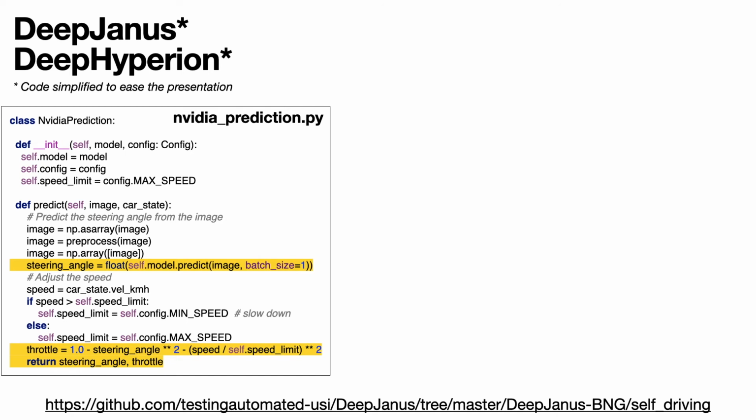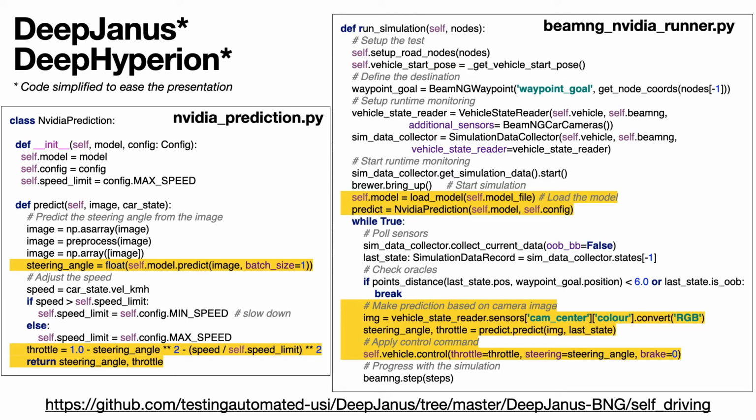Once you have this model, once you have this component available, assuming that you already have a pre-trained model as I do, you can put it into the actual execution. And in the actual execution, what you're gonna do is create your scenarios, defining the road and the initial placement of the car as we have done before, you load your models that specify the weights of your network, and then inside a big while loop, you pull the data, for example, data from the camera, and then you ask this model to make the prediction. And once you have this prediction, you can apply the control command.